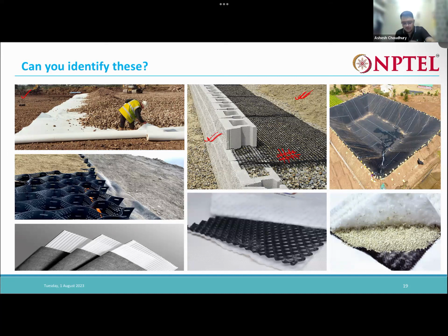Say here we have some granular material, gravels or something. The front portion you see is just a fascia, right? What they are doing is placing one layer of gravel, then one layer of geogrid, and the geogrid is pinched between these two blocks so that it doesn't move.